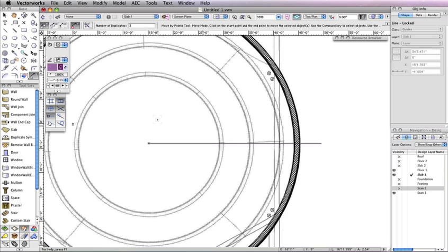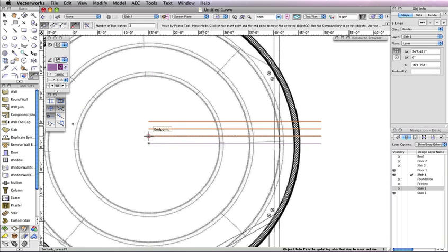After that, click on the existing locus point when the locus or endpoint cursor cue appears, and press the Tab key to enter the length field on the floating data bar. Input 1 foot 6 inches and press the Enter key to lock in the value. Then hold the Shift key and move your cursor upward. When the cursor cue vertical length appears, click to create the duplicate guides with this spacing.